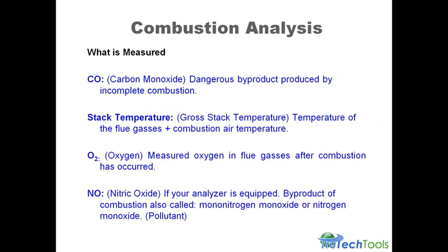So, well, what does it do? Well, first of all, let's look at what's measured. We're measuring carbon monoxide, which is a dangerous byproduct of incomplete combustion. It measures the stack temperature. We call it gross stack temperature because it's the temperature of the flue gases plus the combustion air temperature, right?